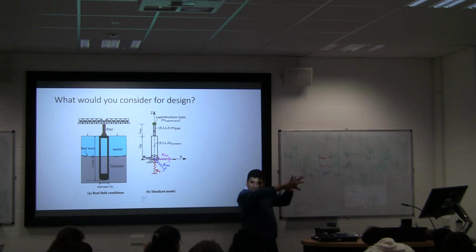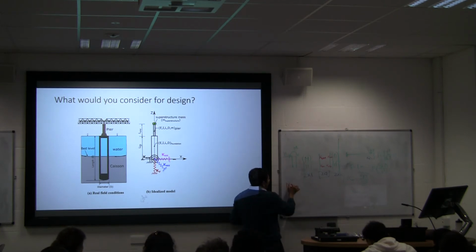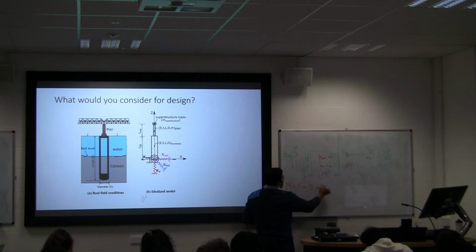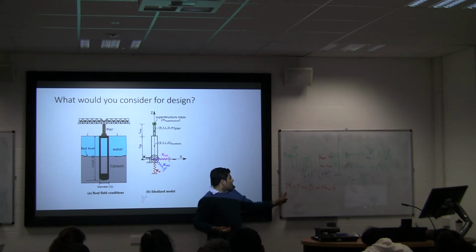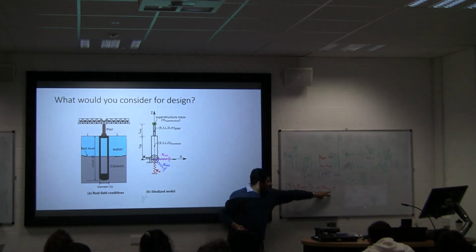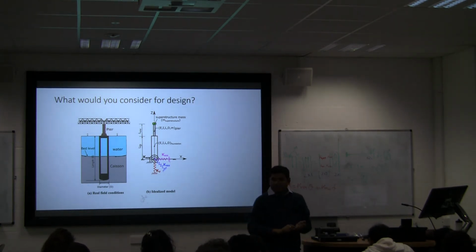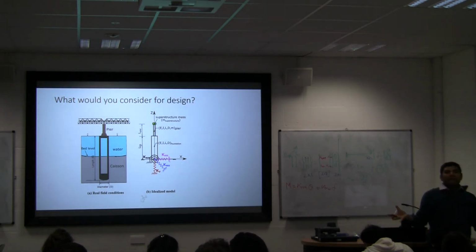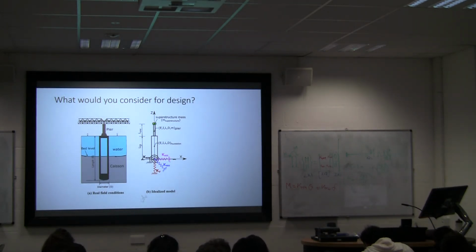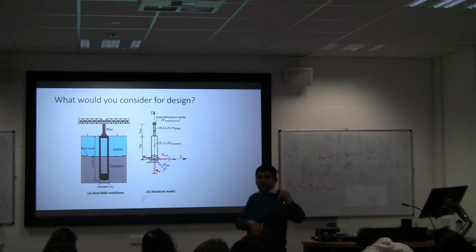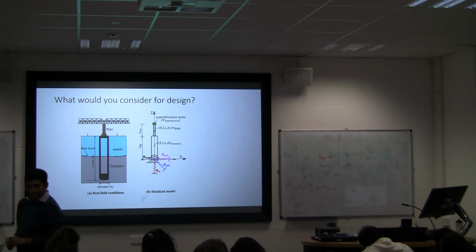So if I now split the whole equation, I get M is equal to KMM theta plus KMH delta. So a moment will give you rotation, but also there's a term due to deflection. That's the coupling term. Okay? Is it clear? That is basically the compatibility of load to the deformation.